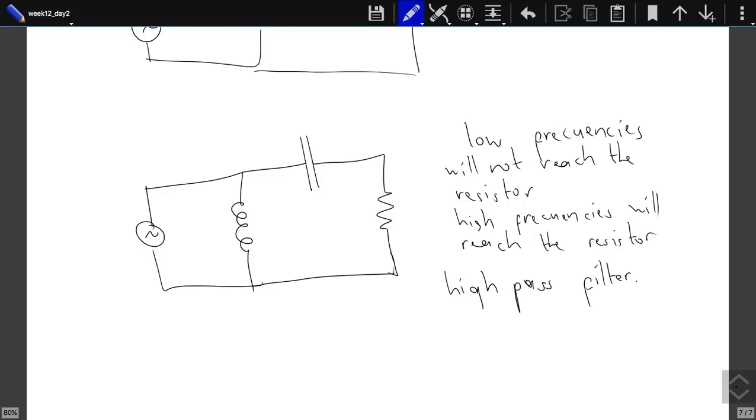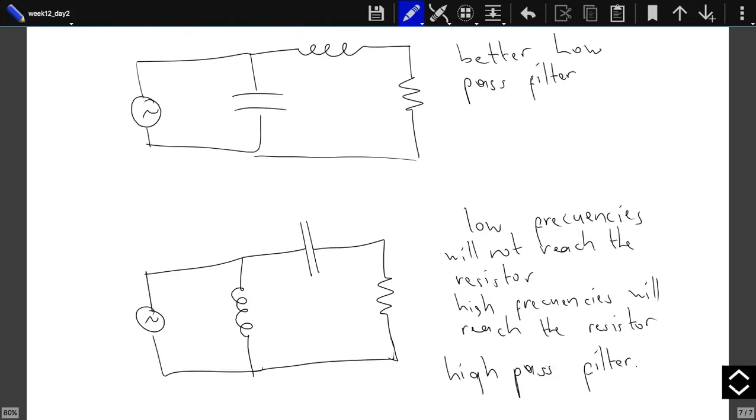Can you say why it's different, this situation? Yeah. You see, the behavior of a capacitor and an inductor. If you attach a capacitor to a DC circuit, after some time it gets fully charged, after a very short time if there is not much resistance, and once it is fully charged, it will not let any current pass. So that is the low frequency.